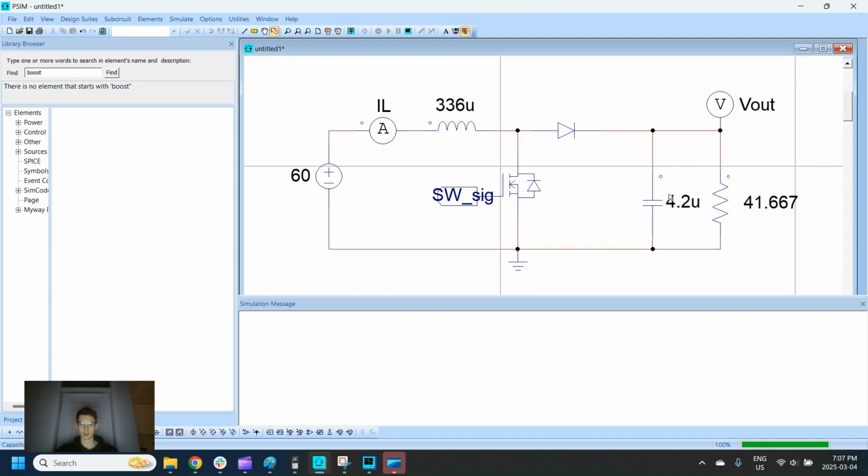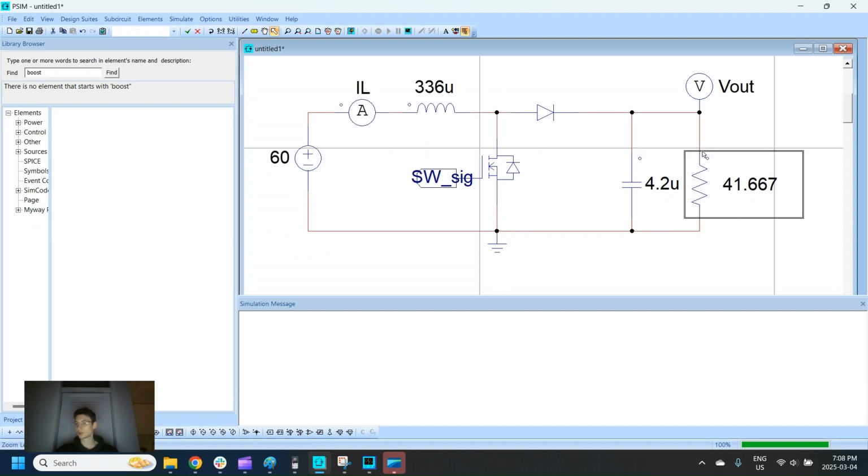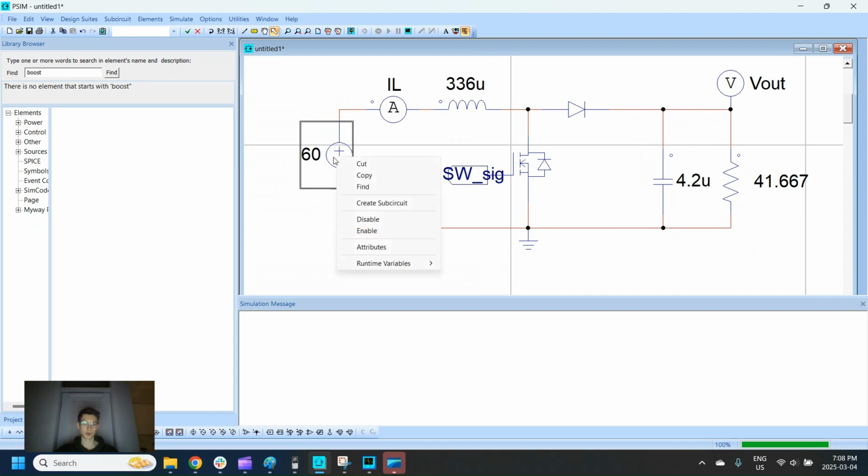Yeah, that should cover everything. So you have your capacitor, your diode, your inductor. Those are all just your passive components that you're selecting. The load will be an external load. The source will be a power supply that you're running. Make sure your traces are rated for the right current. Your MOSFET you're going to select, and then you're going to have a gate driver for your microcontroller. You're going to have your microcontroller basic peripherals, and some sort of voltage sensor on the output that you can send back into the feedback loop.